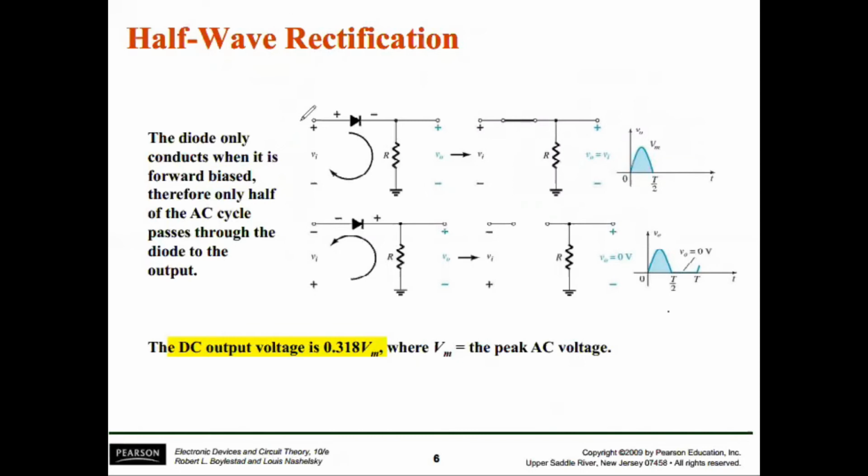So what happens here in rectification is that an alternating current AC waveform is applied here. For the AC waveform, the positive cycle will be conducted by this switch, because for this cycle this terminal will be positive while the other terminal will be negative. For this configuration, this diode will behave as a short circuit as written here, and it will conduct the positive wave through this resistor, so V naught will be equal to Vi, and it will be like this one.